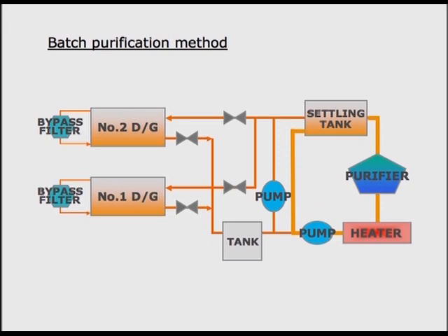Set the cleaning time in such a way that the lube oil of the settling tank flows through the purifier 20 times or more. Regularly carry out the cleaning of both the sump tank and overflow tank.